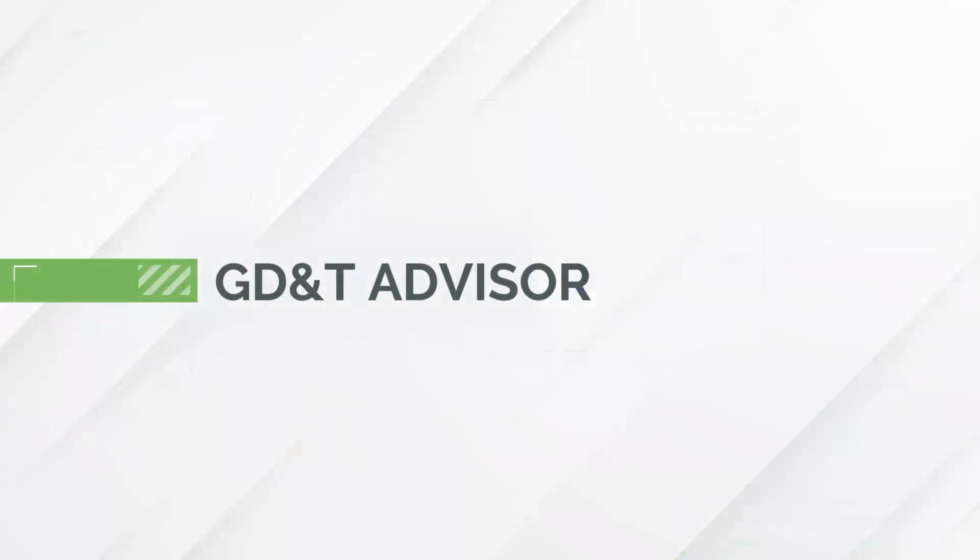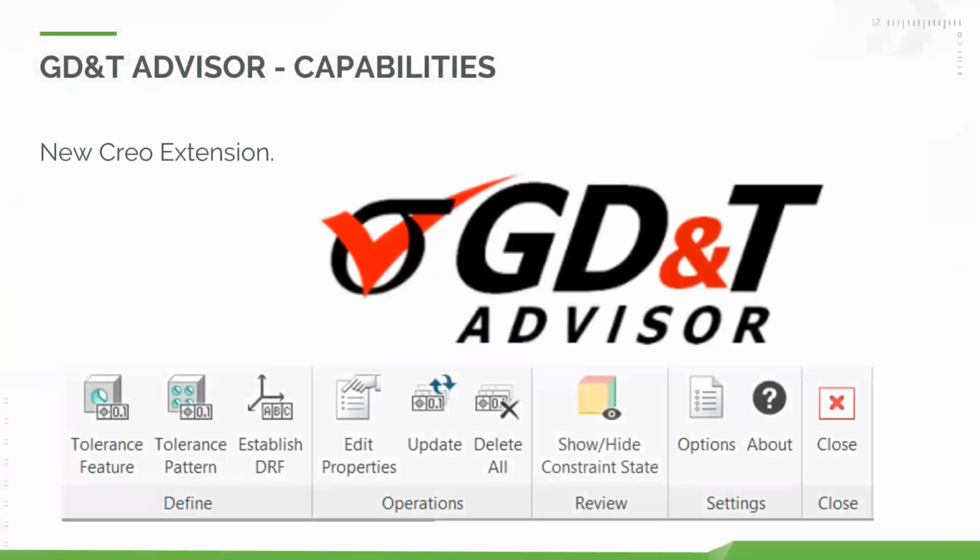Okay. Now getting back to the GD&T side of it, we have the GD&T Advisor that really walks you through the process of dimensions and tolerances. So it guides the user. When you ask for a tolerance, it's going to say, you probably want this to be a profile of a surface, for example. There's some things that would be invalid. You know, if you pick a flat surface, you're not going to want circularity.